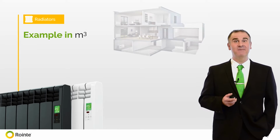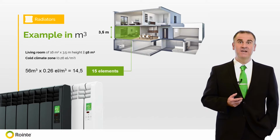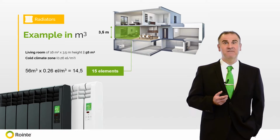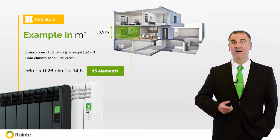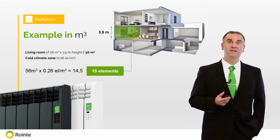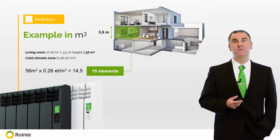If we take an example of a similar size room in a cold climate zone, but with a ceiling height of 3.5 meters, we need now to use a meters cubed calculation. 16 meters squared by a ceiling height of 3.5 meters is 56 meters cubed. So therefore, 56 meters cubed by the RTC, Rointe thermal coefficient, of 0.26 equals 14.5, i.e. 14.5 elements required. Therefore, 15 Rointe elements are required to heat this room. This would ideally be one 15-element Rointe radiator.